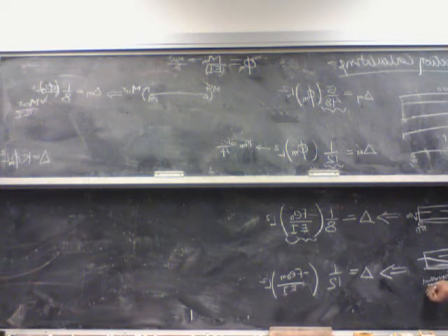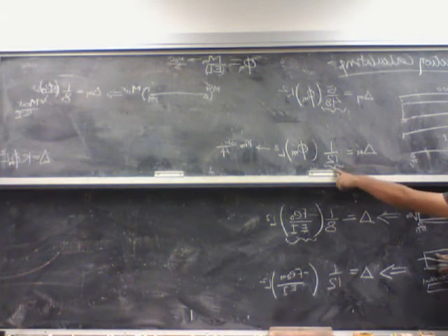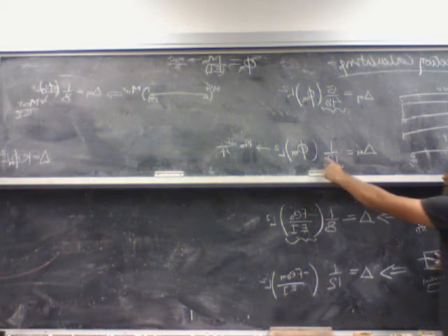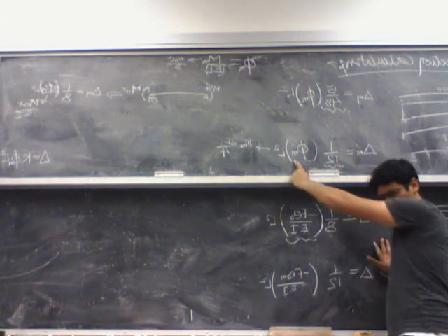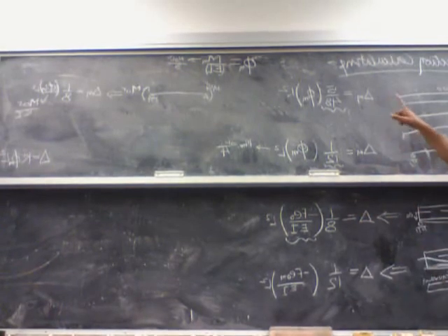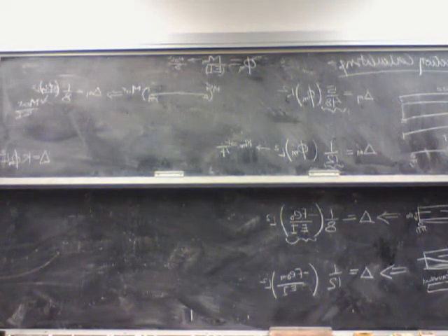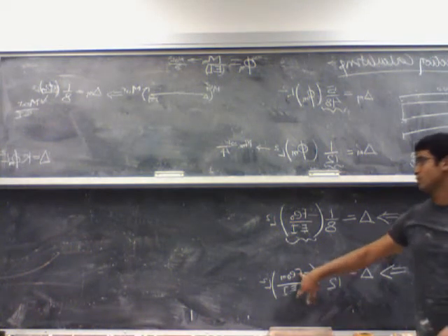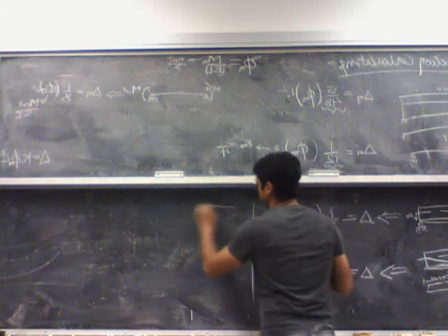You just need to know that, okay, these two are equivalent to each other. And then what you are simply doing is you are simply using this factor, so this factor times whatever is the curvature at the midspan. Curvature at the midspan is simply moment at the midspan divided by EI. Moment is simply F times e naught at the midspan. And I can directly go ahead and use this formula. The next case is